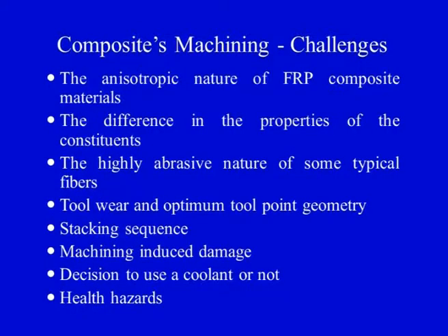The last point is the health hazards. Sometimes the chips that are generated during the machining or drilling operation are never continuous in nature, specifically in case of thermoset materials. So when we do not get continuous chips, the material is removed in the form of small fibers, or you can say a powdery material, and a lot of dust is generated because of the machining operation. This dust should not be inhaled by the operators or the engineers while performing the machining operations, because it can cause severe health hazards.